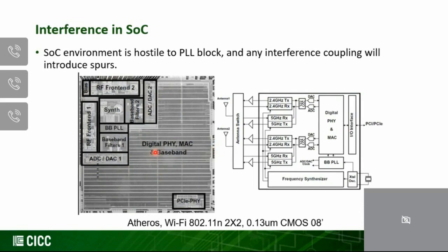And as you can imagine, all this digital portion can be clocking at some frequencies, and you can see that the PLL on the analog side may be picking up that noise through the substrate, it may be through the bond wires, or it can be through the power supply. So this just shows you that it's really, really difficult in today's IC implementation to actually stop those